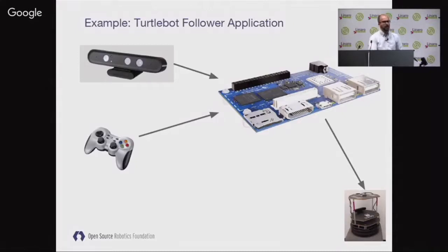So if we look at the hardware that's happening here, we have the Dragon Board 410C, which is the center of this little robot. It has a depth camera that's plugged into it. In this case, we're using an Orbbec Astra, but there's now a pretty big equivalence class of depth cameras made by various vendors around the world. We then have a joystick so that we can turn the following mode on and off or override the following behavior and teleoperate it directly. And then at the other end of the screen, we're plugging in the Turtlebot into the USB ports. So all these things are hanging off the USB tree, and we're trying to then have a way to expose them in a way that is ideally reusable for the vast majority of the software.